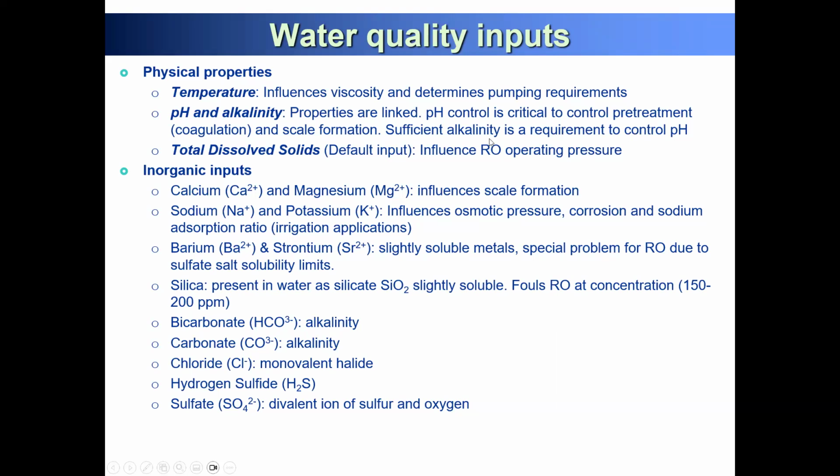If you know the alkalinity concentration of the water, it gives you more detail. When you concentrate your water more and more, you may have a calcium carbonate fouling potential, and the software will calculate this kind of information. So if you give pH and alkalinity, this is ideal to look at the inorganic fouling potential.